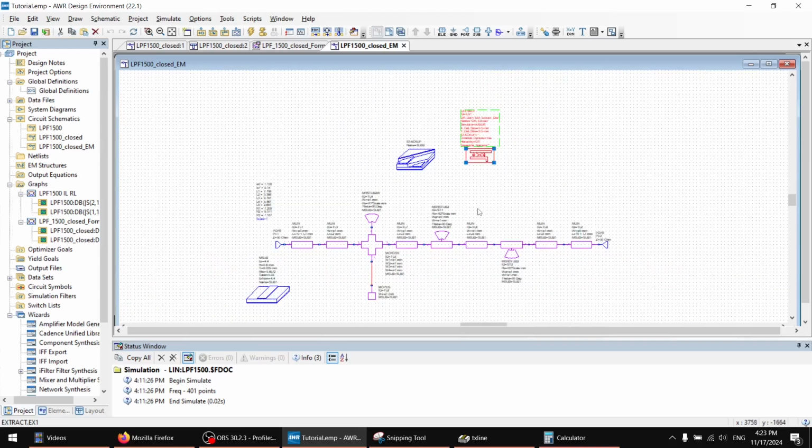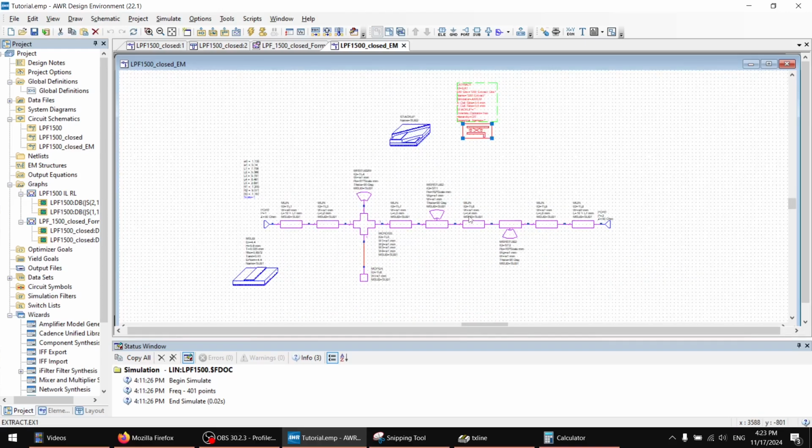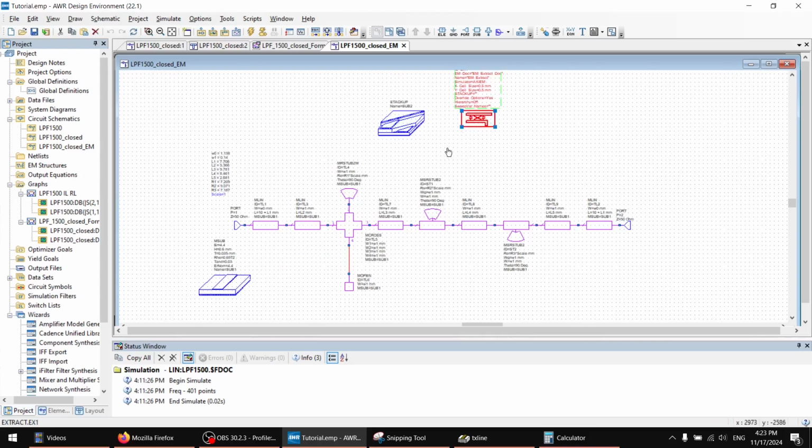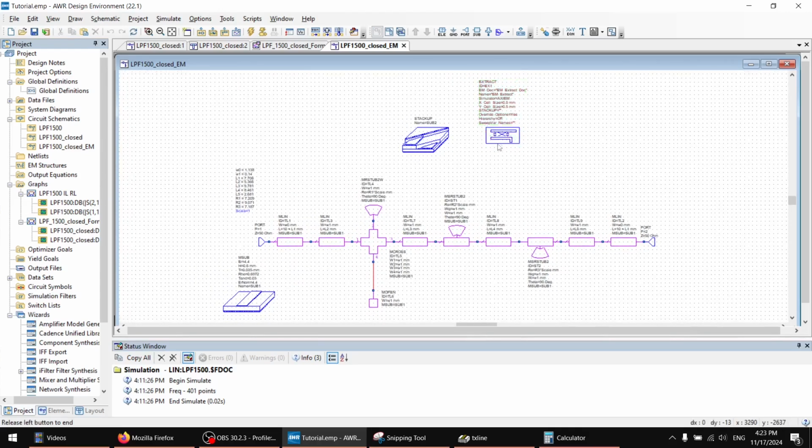And first thing, if you press this once and click on this stack up on the extract tool, nothing seems to change. Now this is not correct. So press shift and select every component. Now with a complex structure, this might take some time.